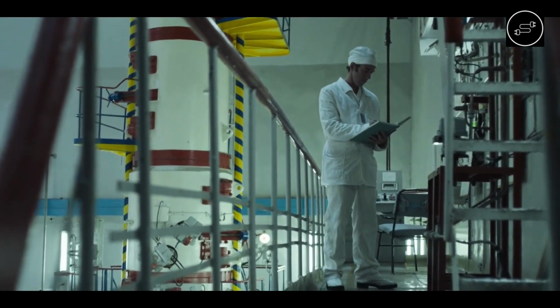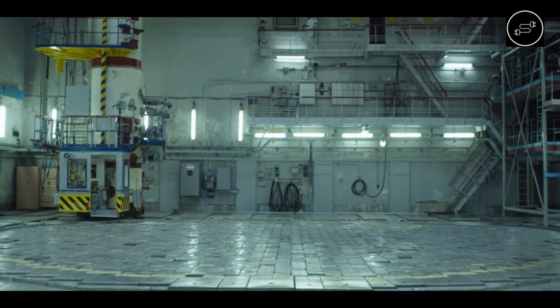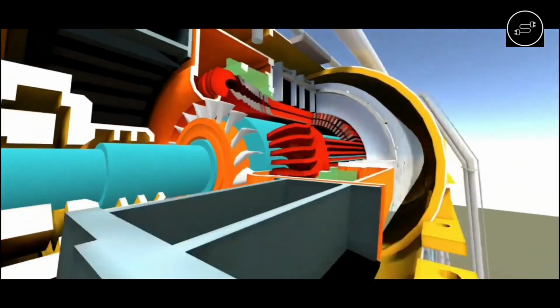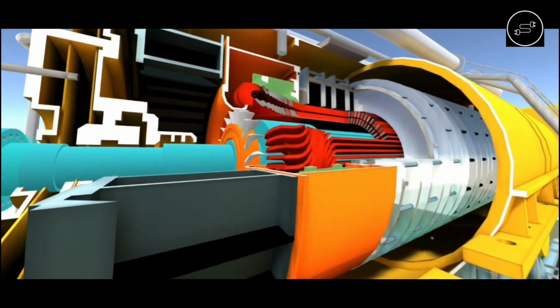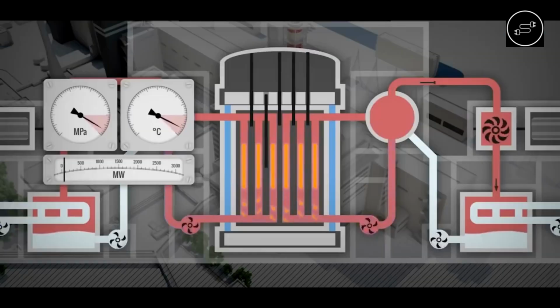4 of the 8 pumps were powered by station service source, while the remaining 4 were powered by the generator. Steam supply to the turbine was shut off, and diesel generators were started. However, the generator's output declined before the diesel generators reached full load, reducing coolant circulation. This led to the formation of steam voids inside the reactor, increasing heat and pressure, making the reactor highly unstable.